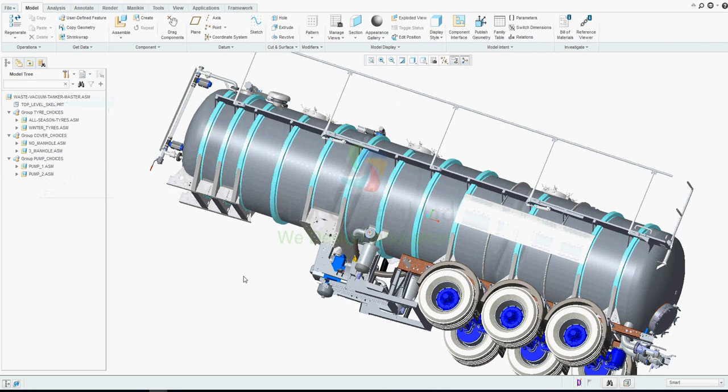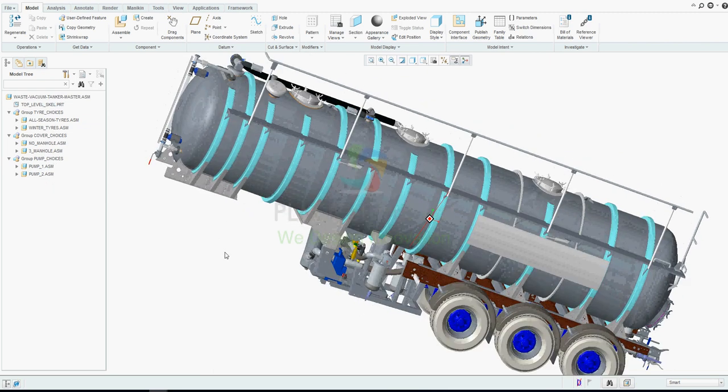But when we look at it from the top level, you can't tell much because they are placed in exactly the same way. The key thing to this method is to have this component, which has been placed as the very first component in the assembly, which is the skeleton. And the skeleton is what holds everything apart in the assembly, and it reduces regeneration failure.